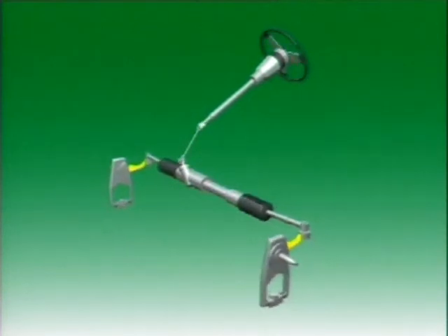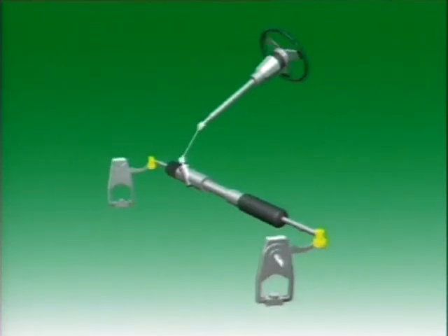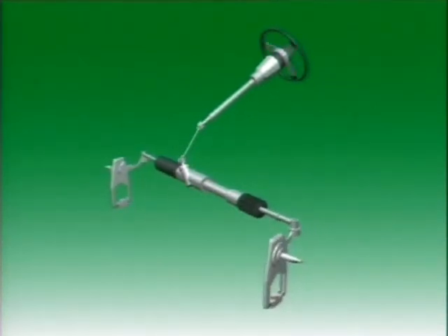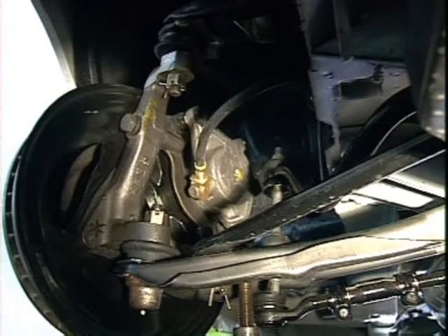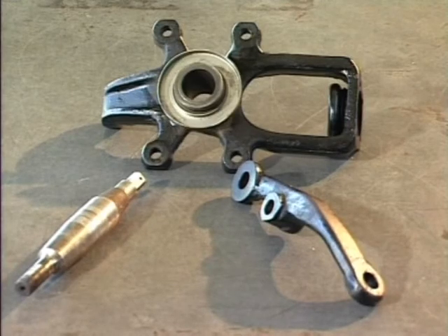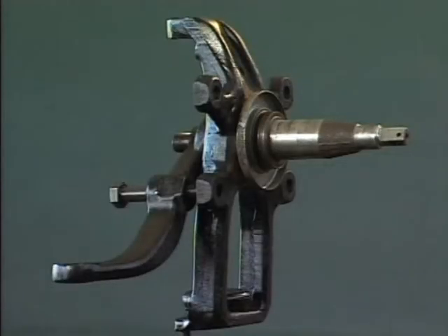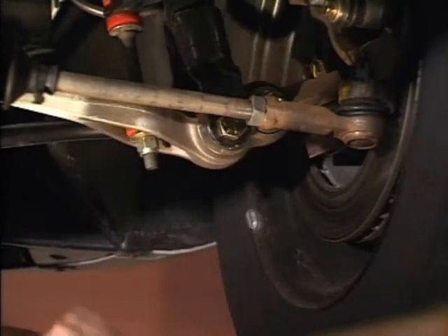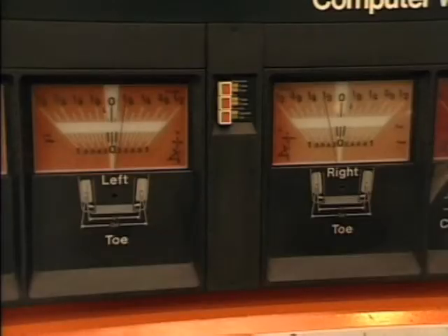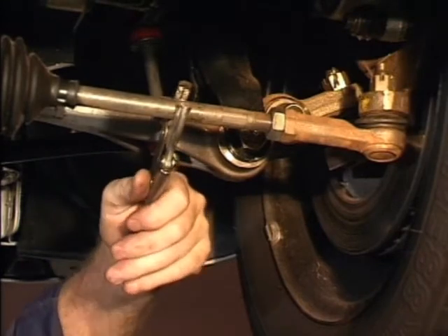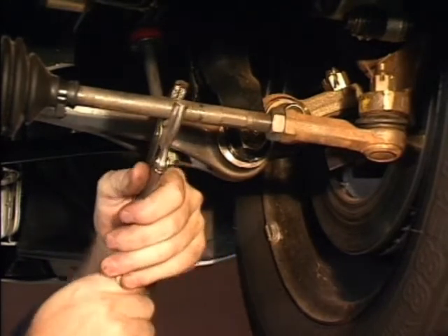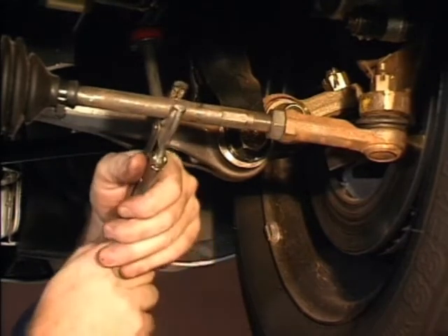The steering lever, or steering arm, is linked to the tie rod, or track rod, by a flexible ball joint that allows for suspension movement and steering rotation. The lever, the stub axle and the stub axle carrier can be forged as one piece and can be referred to as a knuckle. They can also be made as separate units and assembled to form one piece. Each steering system makes provision for adjustment of the linkage to achieve the manufacturer's recommended toe setting. The track rods or tie rod ends are threaded to provide for their lengthening or shortening.